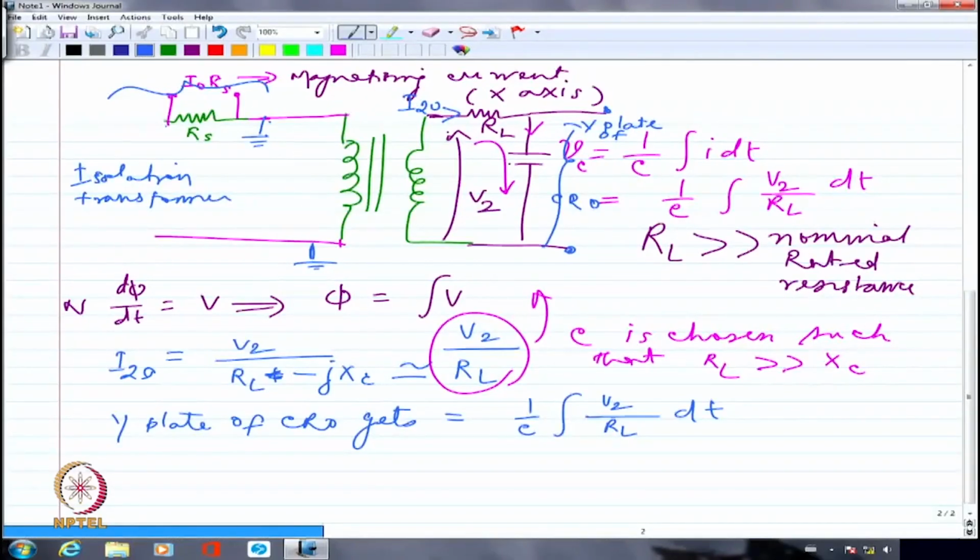So what I will have is an isolation transformer on the input side, like this, and I'm going to connect this to the supply. So I know for sure that probably this side is grounded. It doesn't matter. From here I will connect it to RS and whatever I have to do, and then I will connect it to this transformer.